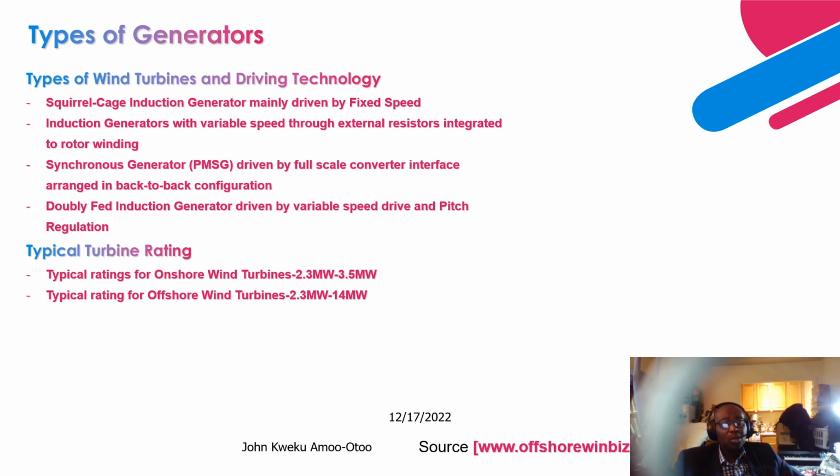It is because offshore wind farms are located in very remote locations, very far from living areas, and there is also a large acreage of sea for us to install these, so it can accommodate a higher rating. In terms of noise emission, there are no living conditions there, so having a large wind turbine that can make a lot of noise is not a concern. Also, the goal is to leverage that large acreage to achieve a higher wind farm rating.